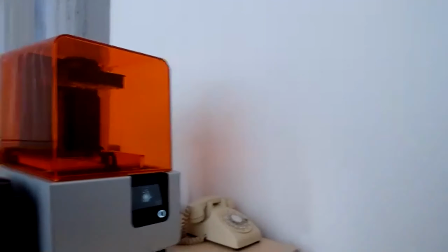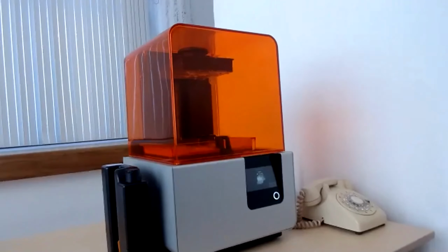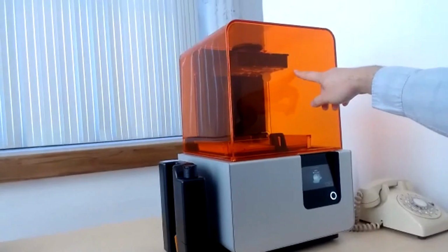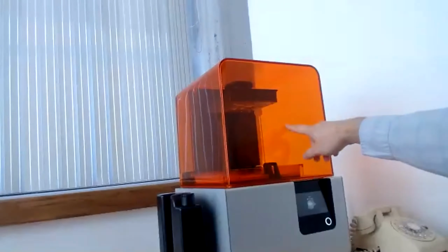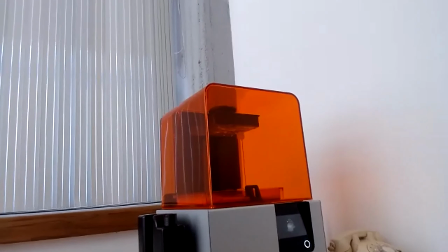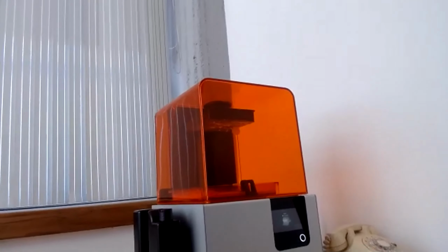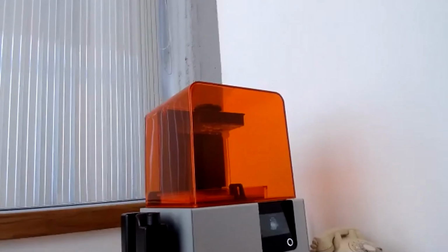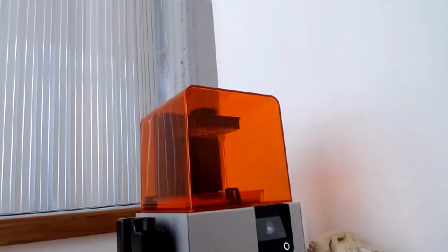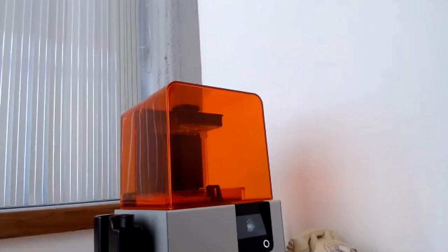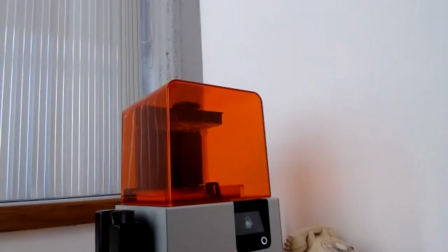This is the maximum I can go right now. And this part is there over there. And as you see, we have liquid all over there. So that's why I will wait for about 5 or 10 minutes and then do the second process, which is washing. We will be washing it with IPA. And then after washing is complete, I can do the post-curing operation.